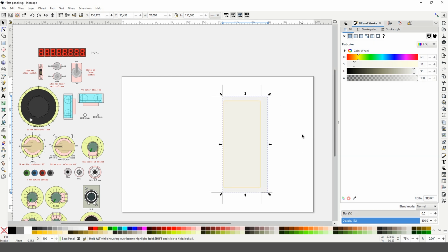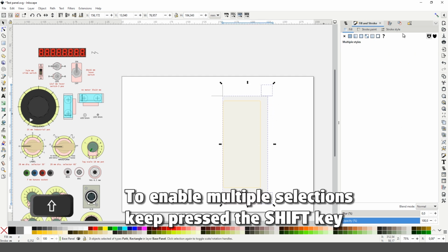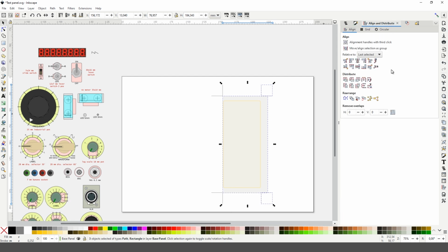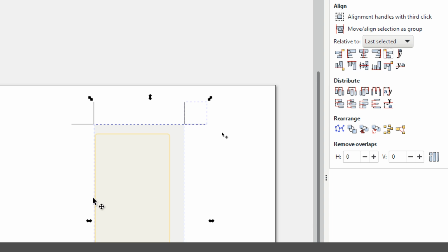Once resized, you can realign the cutting guides, that are these squares, these angles here, this square here. So select both, then select the panel, go to align and distribute, and select this one. The yellow part is the reference, while the gray, pale blue parts are the parts that move with the alignment. The red line indicates the point of alignment. So let's click on this, and voila.